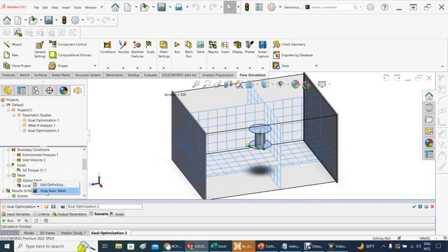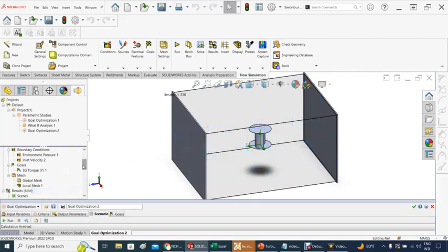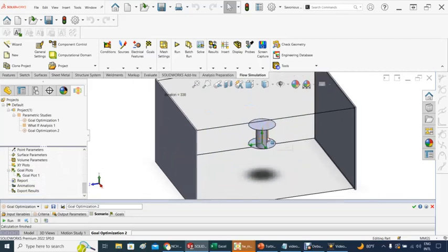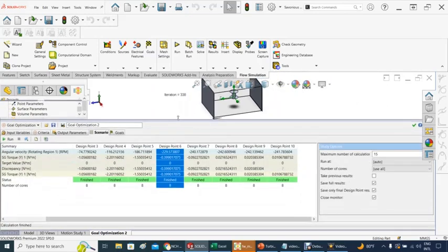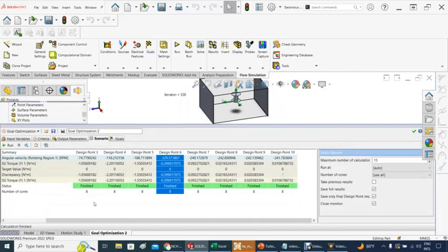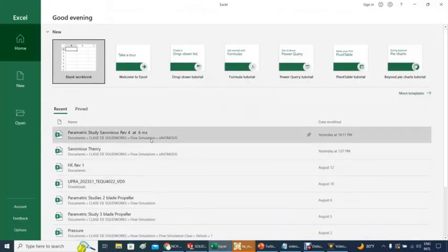Mesh. There we go. Now, again, that's basically it. It's kind of predicting, we'll say, roughly the numbers start to look good in terms of watt production at the wind speed of 13.6. You can tell that by the data that I did here on the goal optimization. If we take this data to Excel, then we can analyze the torque and the RPM, and with that information we can get watts. I did that, so let me open up that here.